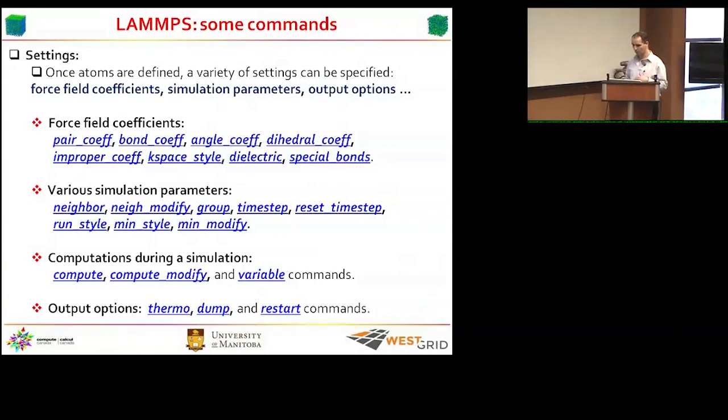Now, in the same input you can run multiple simulations, but it's not recommended, because whenever you run an MD simulation, there are three different steps. The first is the preparation of the simulation. The second is running the simulation. The third is post-processing the data. Because, for example, if you run an MD simulation using NPT, the density of the system will change as a function of time.